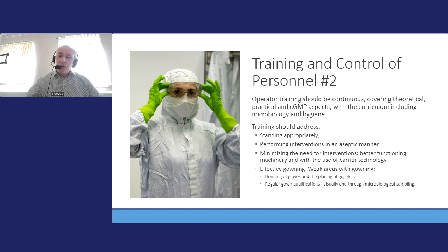important. And for those people who are tasked with running aseptic processing lines, then there may need to be an extra layer of training, particularly for those who are required to perform interventions into the aseptic core as well, and including things like airflow visualization studies or smoke patterns, and showing operators what happens when disruption occurs, or using things like UV fluorescent fluids, and then using UV lights to show what happens if you miss certain areas of cleaning.